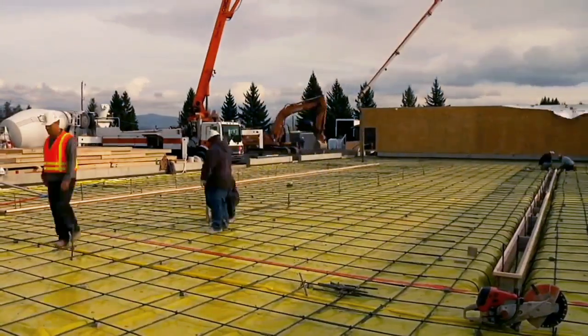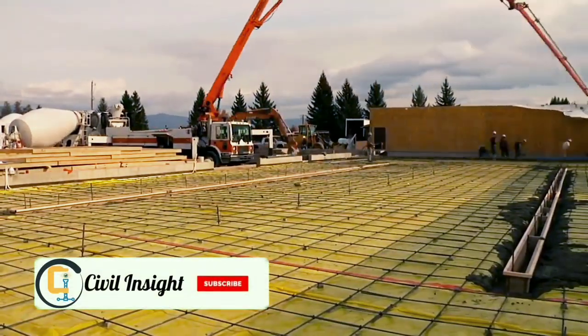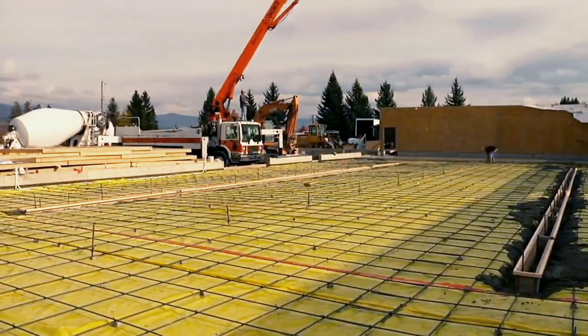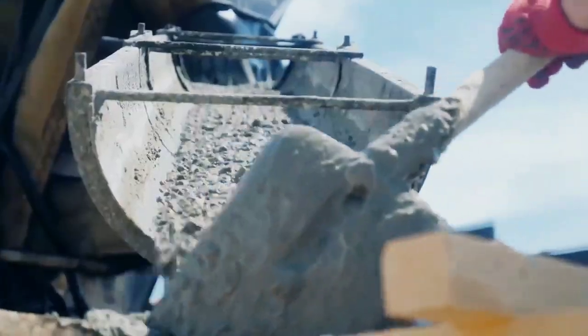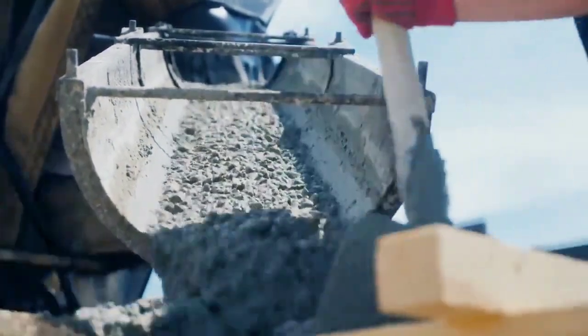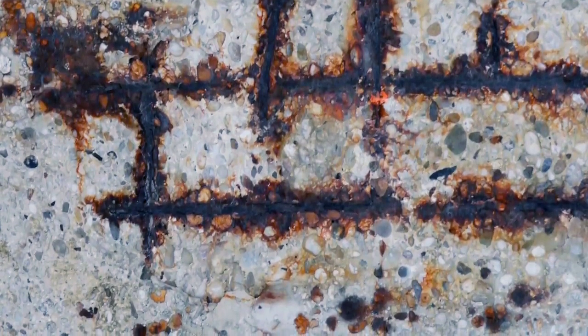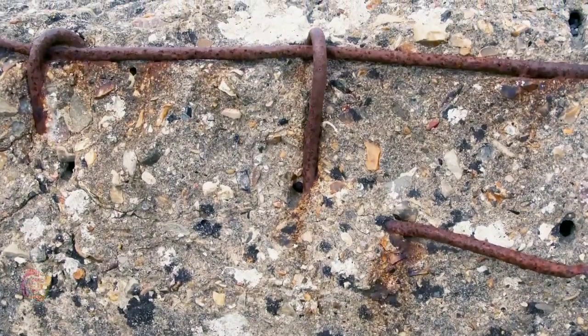Concrete cancer is a serious problem that occurs within concrete, and it is caused by the steel reinforcing inside the concrete rusting. As the steel reinforcing rusts, it expands, causing the concrete around the steel to be displaced. As the concrete becomes more displaced, more water gets into the steel, causing more rusting, and the problem gets worse. The expansion of the steel causes the concrete to delaminate, and results in spalling.